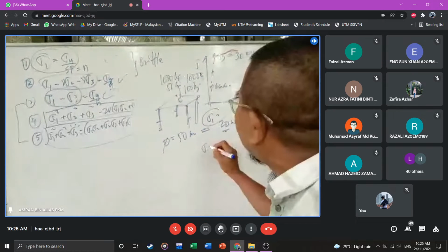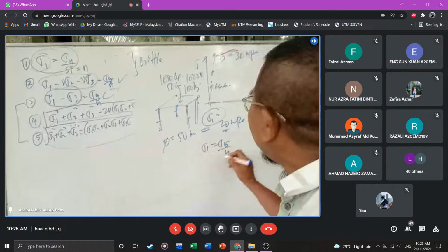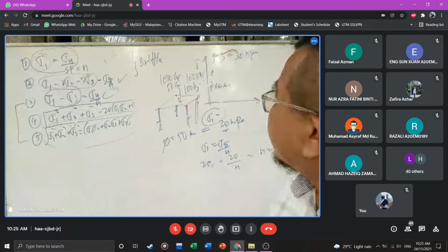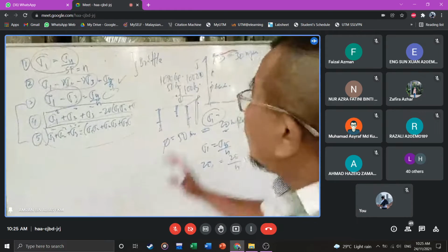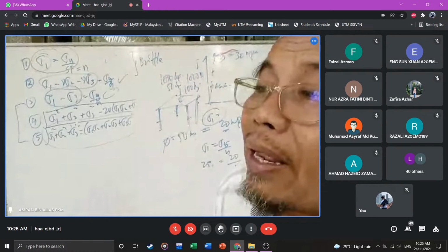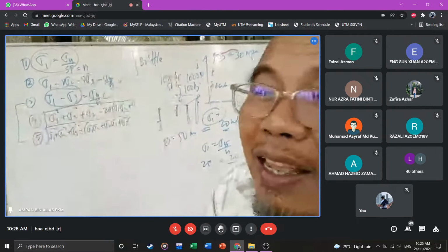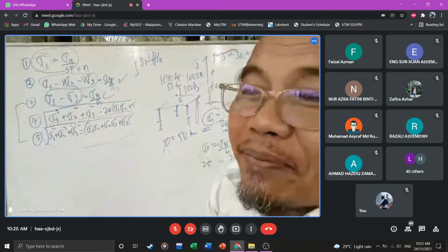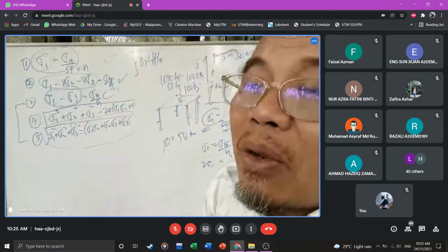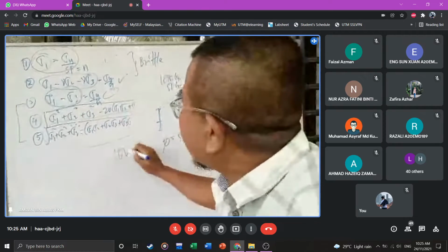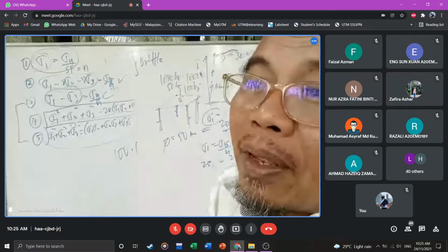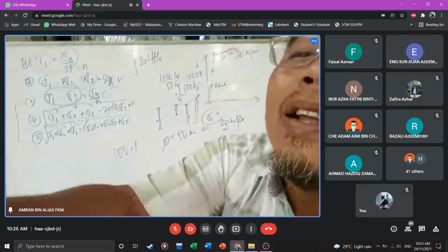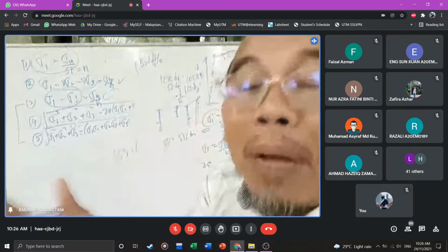So the safety factor is sigma 1 over sigma Y, n. It's 20 there, and the limit is 20 there, so your n is equal to 1. Why don't we want to have n equal to 1? Let's say that day he wears a little bit of a jacket, and the weight becomes more than 100, maybe 100.1 kilogram. So the chair fails, right? Fail. This is what I call an example, to make you understand.